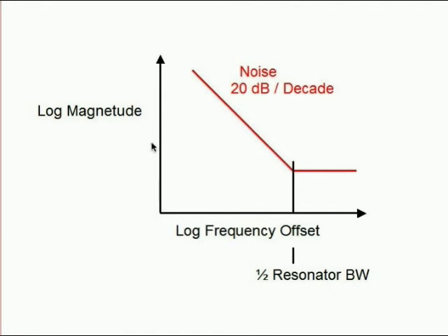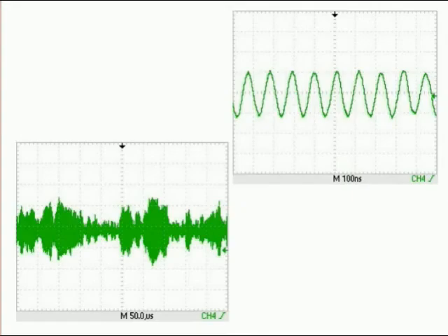Well, I've made some hardware to see whether a practical oscillator would actually do this, just to prove that if you build a practical oscillator that's completely linear, it will have amplitude noise and phase noise that follow the same sort of law. It's not very easy to make an oscillator do this, because, as I said, the limiting has a very powerful effect on stabilizing the amplitude, because in a normal oscillator the input signal is so small compared with the output signal.